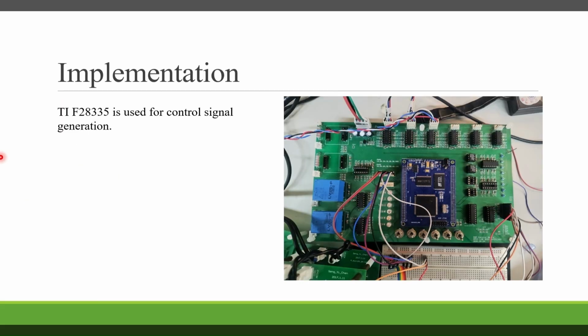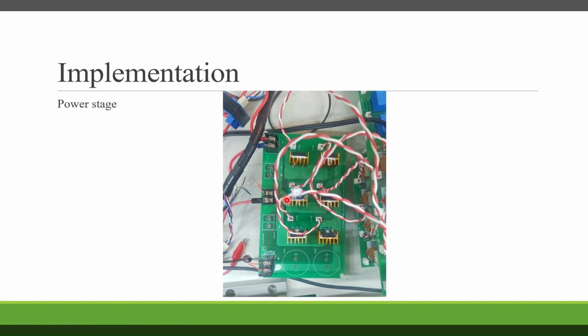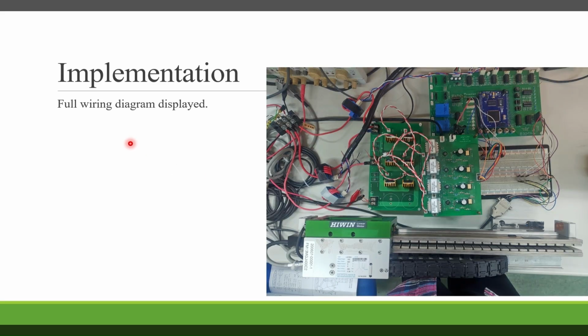This part is the implementation. TMS320F28335 is used for control signal generation. Driver circuit shown here amplifies control signals. Power stage is shown here. This is the full wiring diagram.